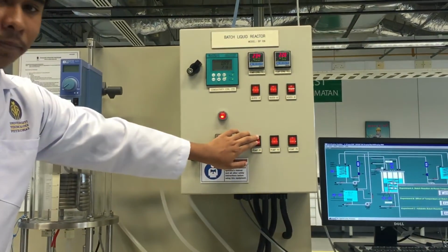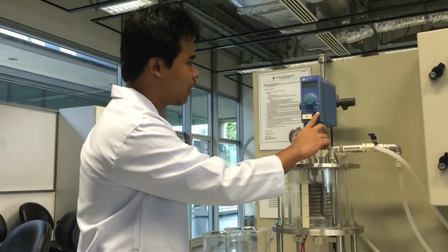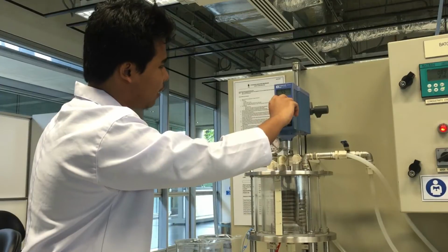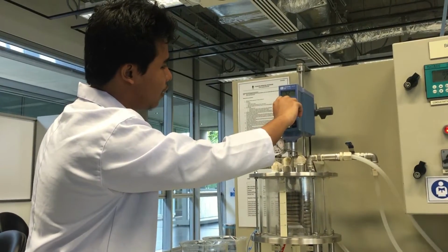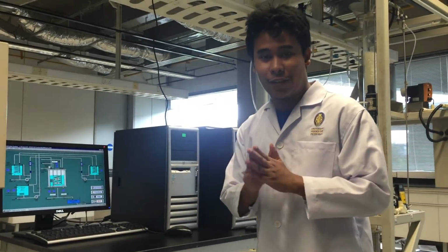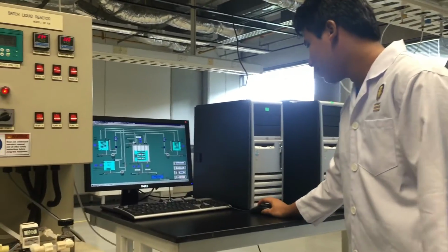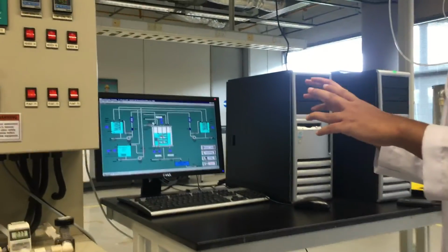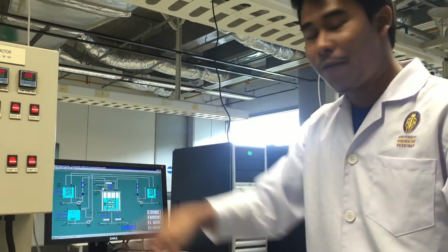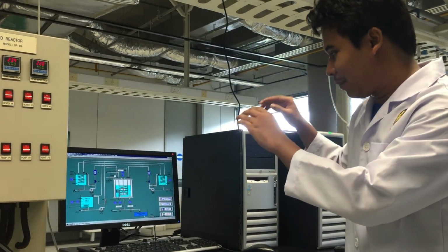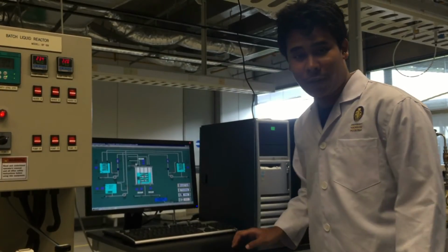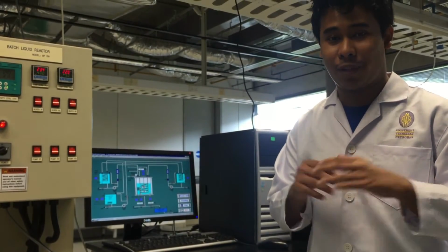After the 1 liter of 0.1 molar ethyl acetate has finished being added into the batch reactor, we must close pump 1. Then we must switch on the stirrer and set it to 50 RPM. Then, using the computer software, we start the experiment. This software gives us a conductivity value from our reaction, and we must record it in the appropriate table. After we get a constant conductivity value, we stop the experiment.